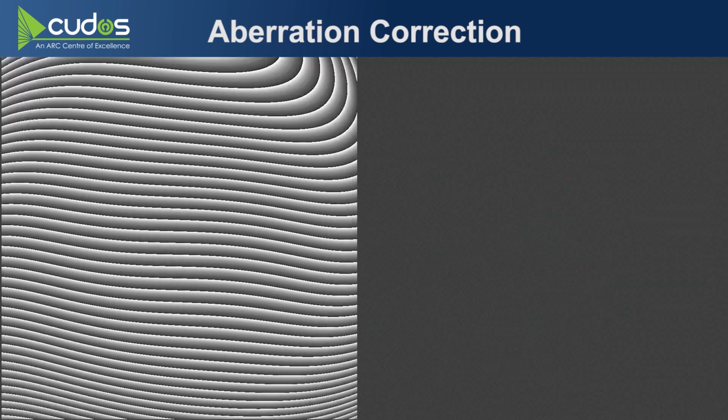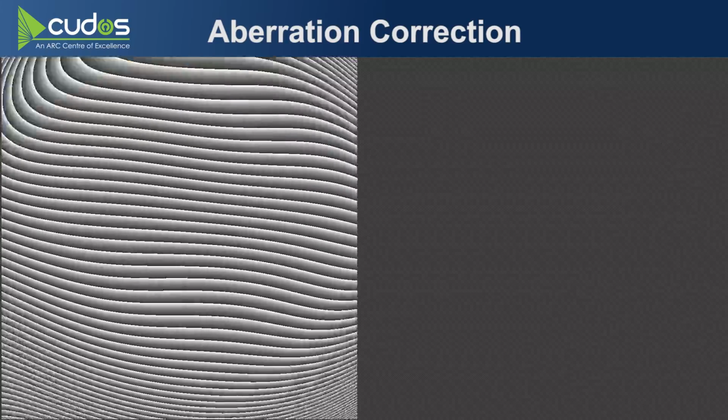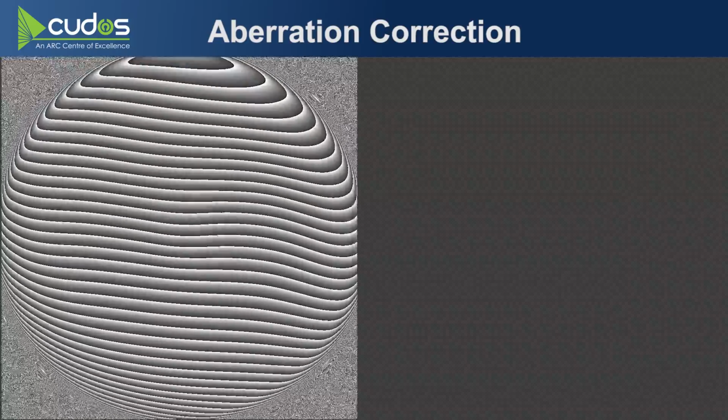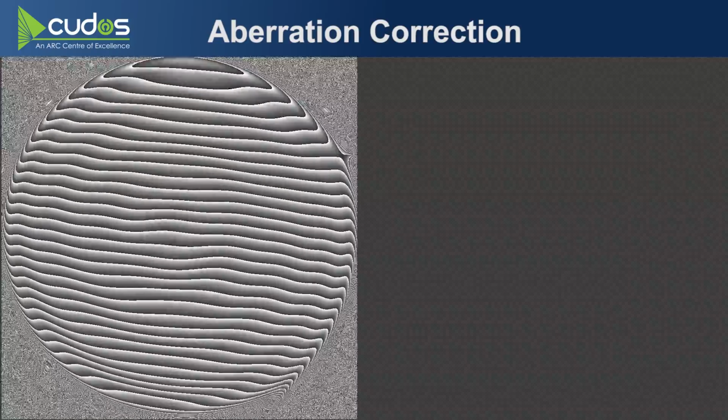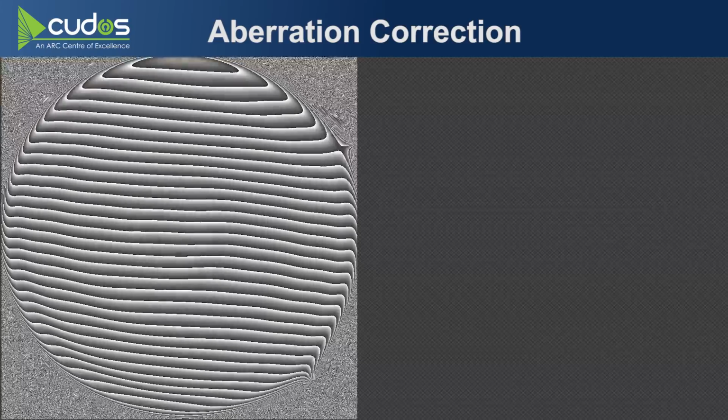But if you extend your alignment process beyond just trying to find the XY position of the fiber, and instead use the SLM as a wavefront sensor, we can calibrate all those aberrations out as well, measured in situ.